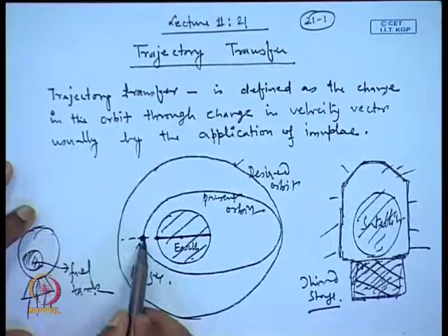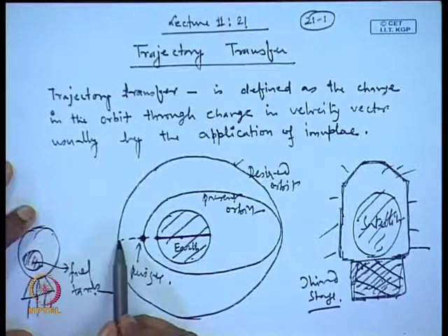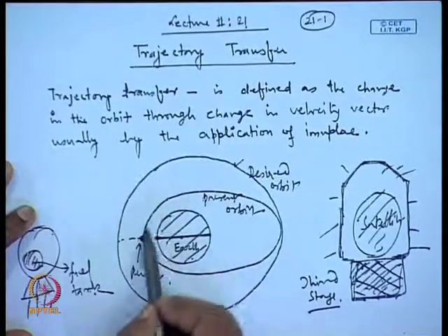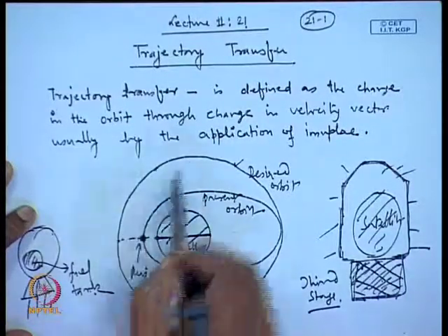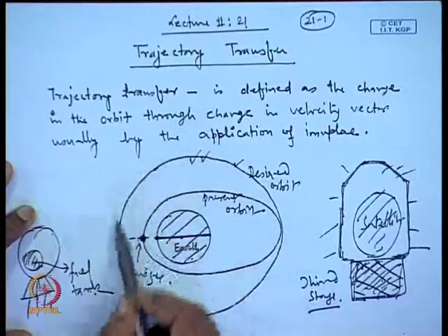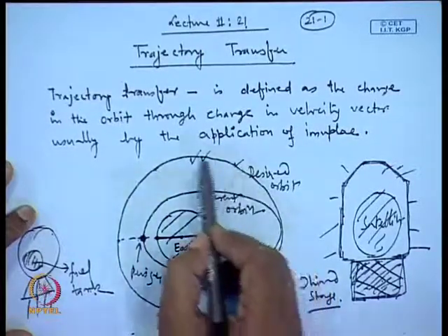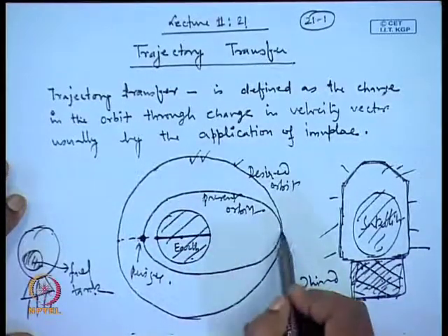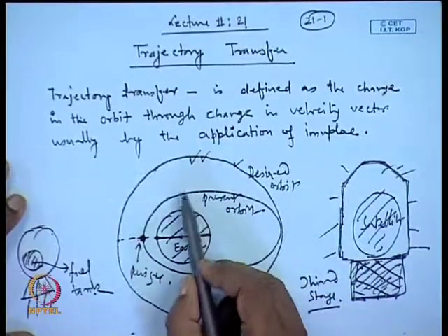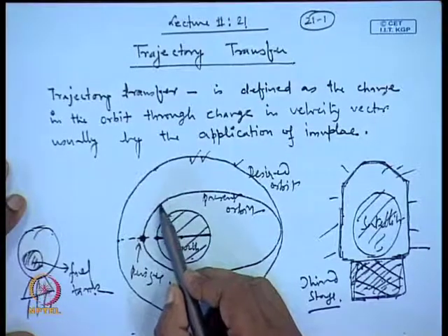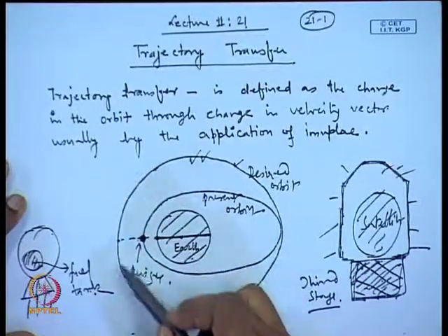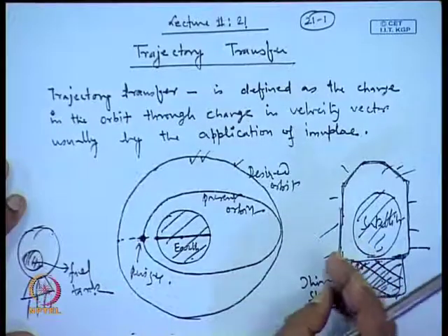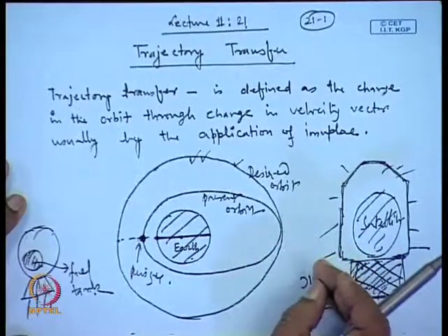You need to boost the perigee, which is also called the raising of the perigee, and once you raise the perigee and the velocity while raising it matches with this circular orbit, the satellite will really follow this course. This way you can precisely control the position and velocity of the satellite, and therefore you can put it in the desired orbit that is really required.